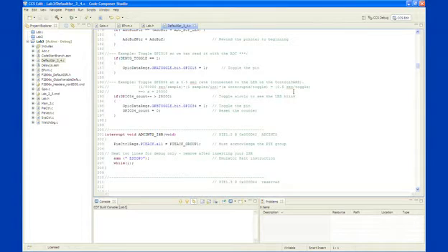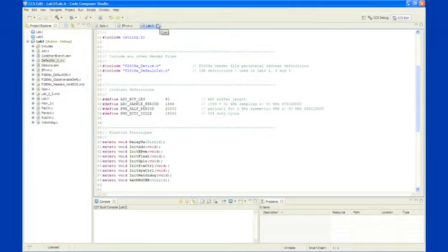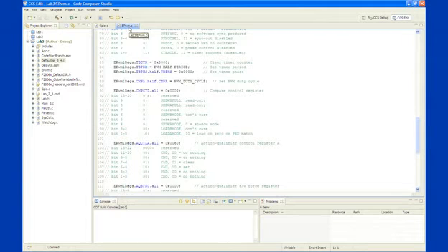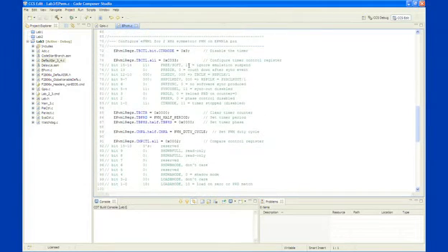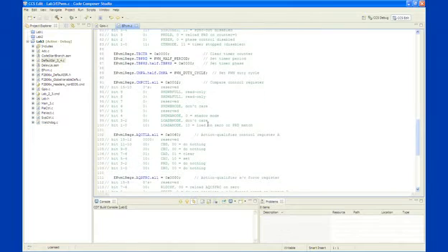This will serve as a visual indicator that we're getting in and out of the ISR, number one, and number two, we will use this again in the flash lab as proof that we actually flashed the device. So at this point, that's pretty much the main pieces of code. We've taken a look at the ISR. We understand now where the constant definitions are being used in the EPWM.c file, and setting up the EPWM module itself.